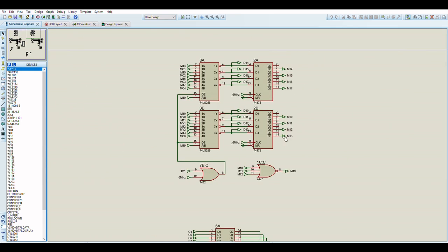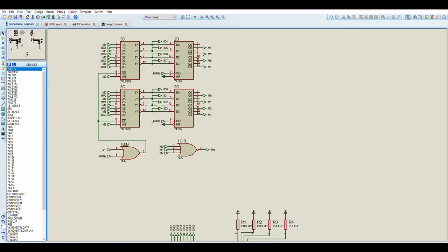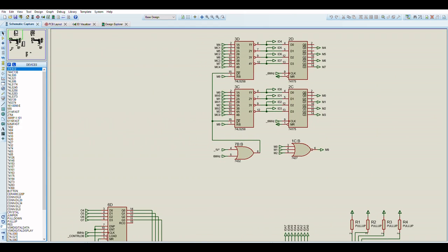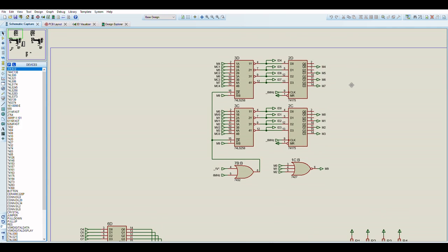What happens is that the lower 3 bits, M0, M1 and M2, are passed through a 3 input NOR, and this basically asks the question, is the current content of the scanline RAM transparent?